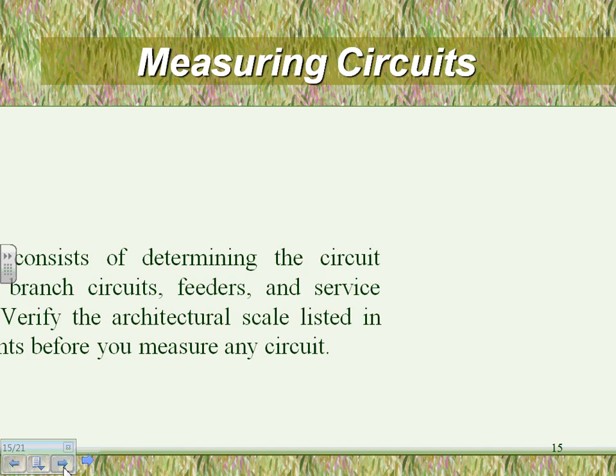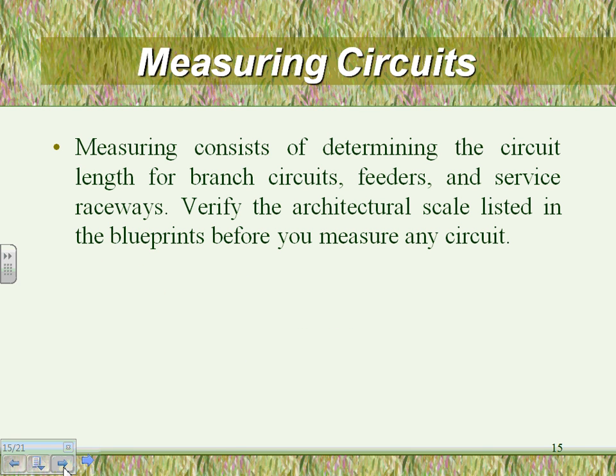So the quantities. Let's go quickly into measuring the distances. We counted the equipment, now we need to measure. The first thing you need to do, and a lot of students mistakenly skip it, is justify the scale on the 2D. If your scale is 1/4 to 1, it's completely different than 1/2, 1/8 to 1, or 3/4 to 1. You can screw up and cut yourself by half if you go from 1/4 into 1/8 scale. That affects your distances.